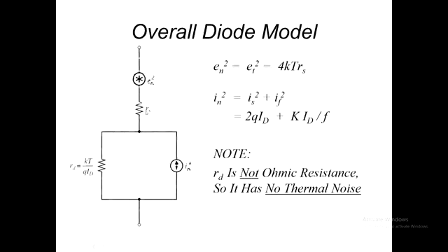There will be, due to the component pigtails, you've seen diodes, they're just like resistors, the ones that we have in the lab. So there's some resistance to where the action is inside the diode. So the leads themselves, they're like wires. So they've got some resistance, maybe a fraction of an ohm, but it's a resistance nonetheless.